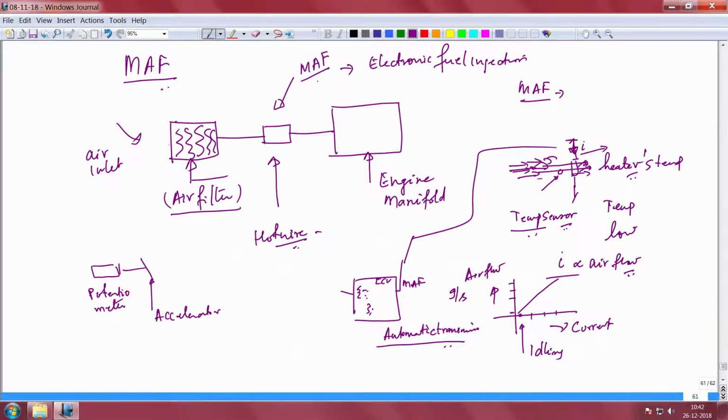While on the one hand the worst suffering is happening to humans, it is not that cars are anywhere safe also, they are also having this problem, because that whole particulate matter will come and sit on this air inlet, this filter will have to work twice, it gets contaminated faster, and if it gets saturated then the MAF will go bad. So, if you buy an expensive 1 crore rupee car, and if its air filter is contaminated quickly, the MAF sensor goes bad.